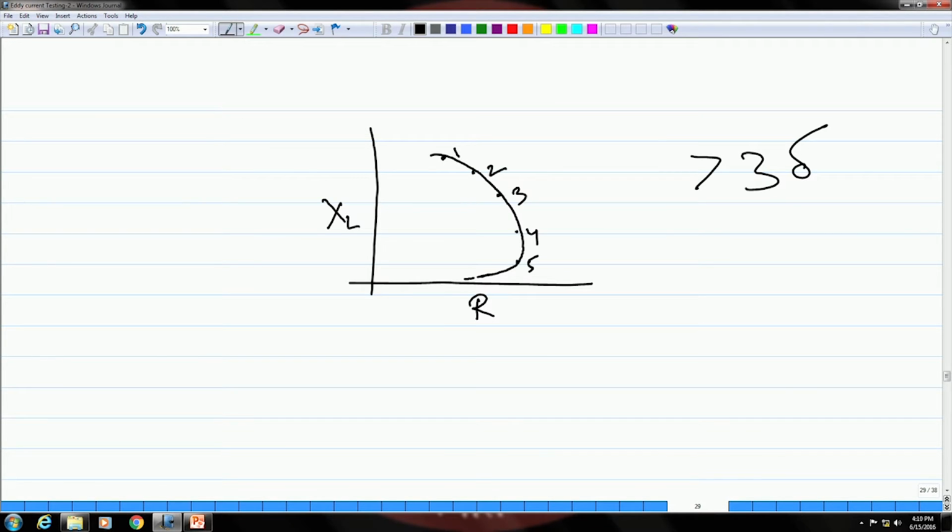So, at this particular depth or thickness, you can call the sample a thick sample, beyond which the eddy currents will not be able to penetrate, because at such thickness, where it is more than 3 delta, the magnetic field of the eddy current will be completely trapped by the thickness of the material. That is why this is called a thick sample with respect to eddy current, beyond which you will not be able to penetrate the eddy currents. So, this is the effect of sample thickness.